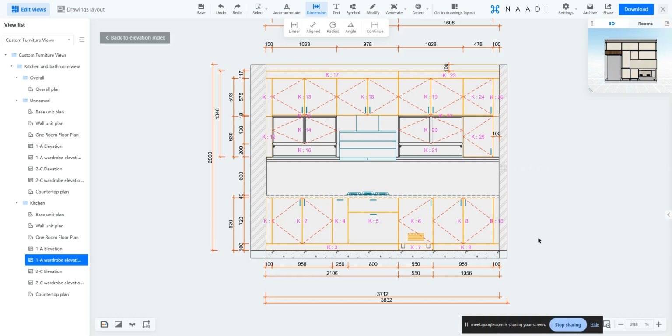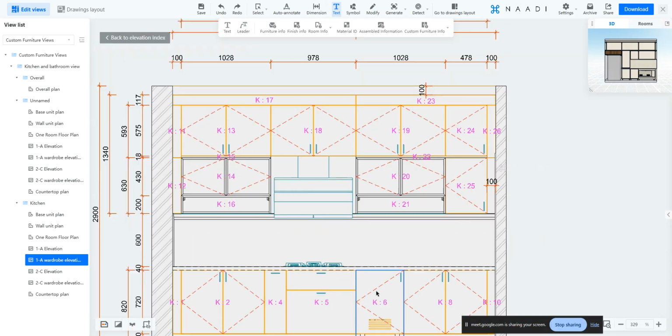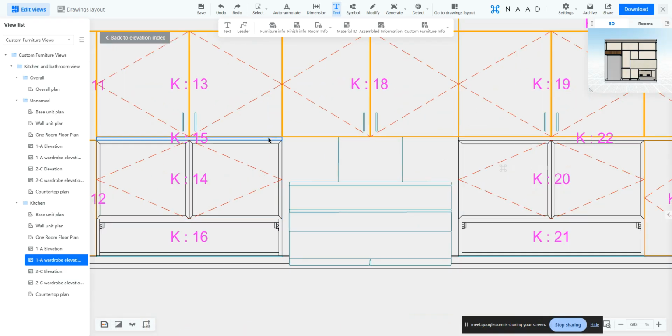The second thing which you want to manually add here, like I said, apart from the missed dimension, is your annotations, right? So you can just do that. You can just go to text, and there you will see text and your leader. Just add your annotations here. Because I could notice, many organizations have a practice of adding an annotation at this point in these segments, and you will take it forward, right? You can do that too.